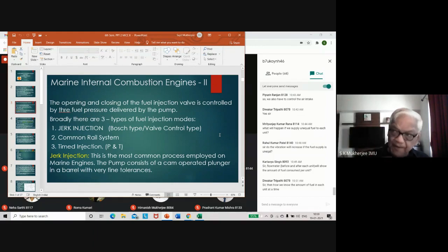Priming the line from the pump to the injector means purging of the air inside that pipe. If there is oil and if there is air, when the pump pumps, the oil is not going to go into the injector. That air is going to compress and decompress, compress and decompress. Each time the pump works, there will be no fuel injection. So it is imperative to ensure that at the highest part of the fuel injector and pipe, the nut is a little loosened and the air is allowed to come out. And the moment the oil starts coming out from there, you close the nut.